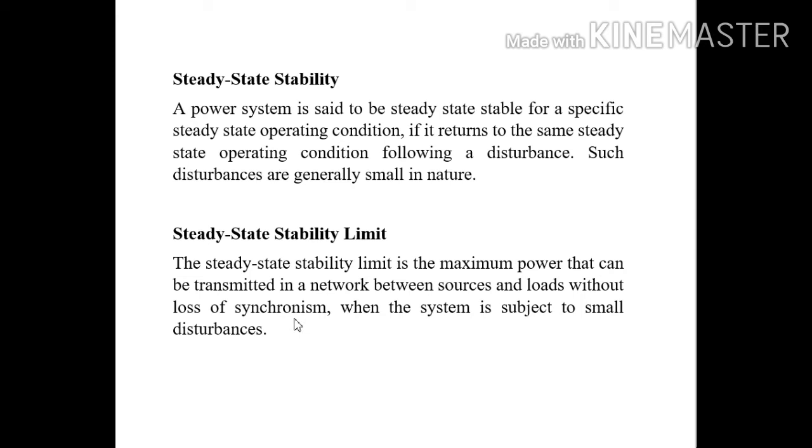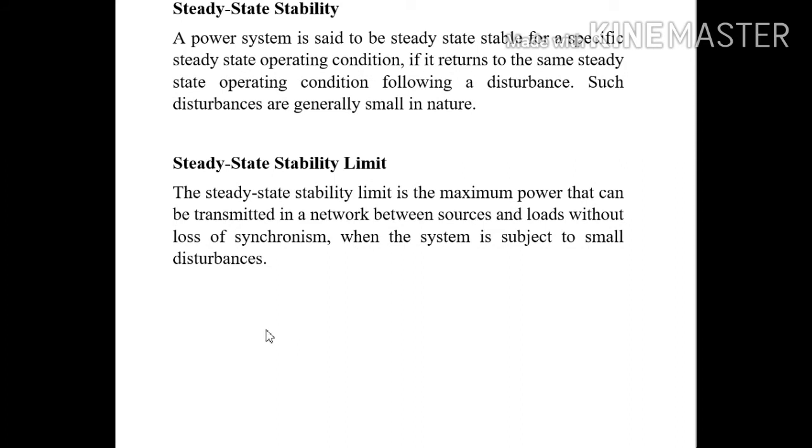So this definition needs to be made more precise. In what manner? In the first place, where should power be measured? That is very important. From a practical point of view, received power is important rather than sent power. This is to be understood even if not stated explicitly in the definition. What is important is the received power. And we know that there is no advantage in sending more power into the line. It does not increase the received power but increases only losses. This is the first consideration.